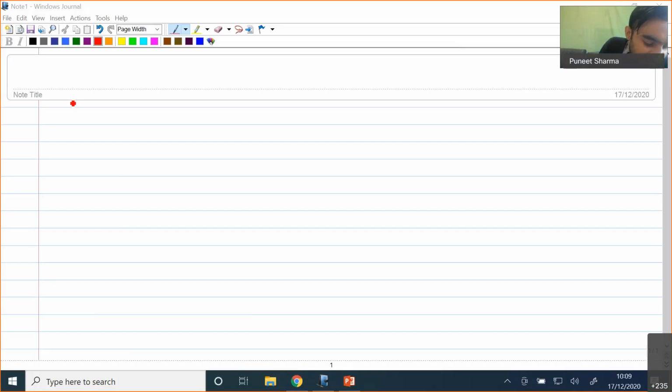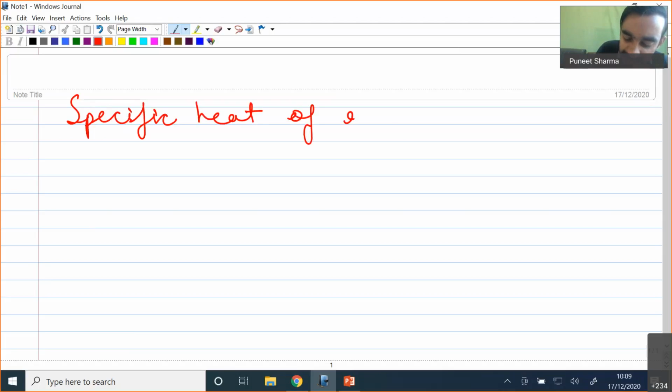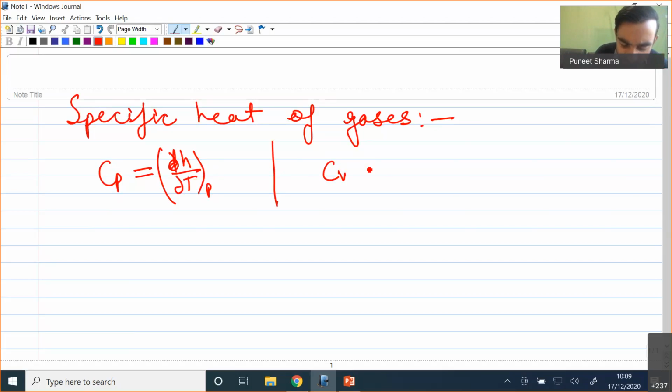Now let us deal with the next topic, which is particularly related to specific heat of gases. So in terms of gases, if I give you the main formulation of Cp and Cv, we have seen that ∂H/∂T at constant pressure is Cp, and Cv we have seen as nothing but ∂U/∂T at constant volume.